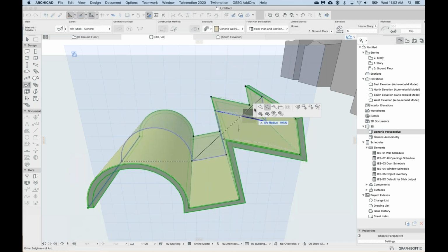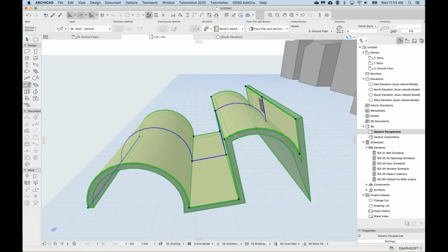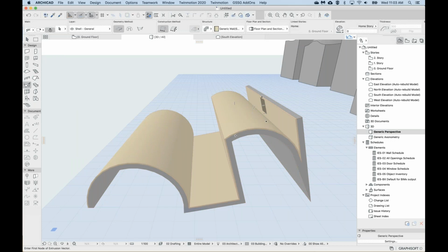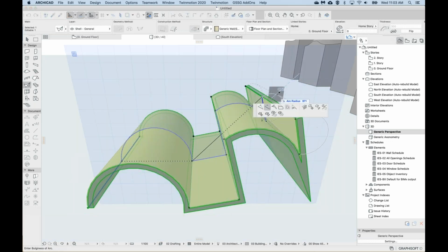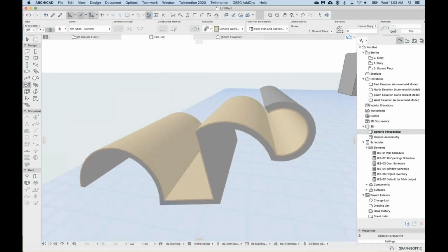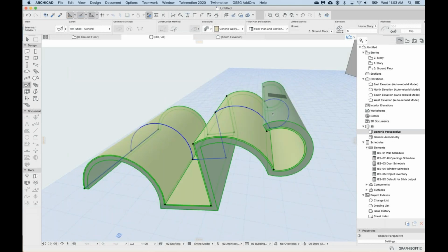So for example, one of these straight edges, I'm going to just curve. Maybe this one I'm going to curve as well. Nice. Yeah, so we can do the same sort of editing on this polyline, and it just gets extruded. And you can see that the shape that it's extruding is a composite. So I can choose any type of thickness or any composite for this extruded element.